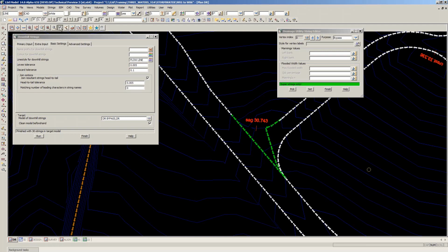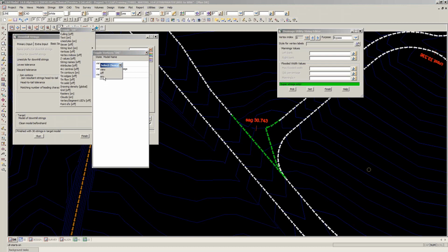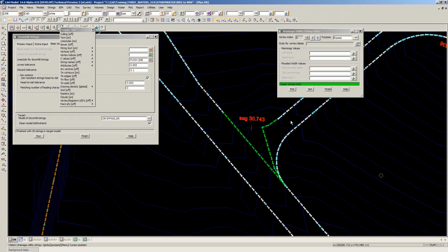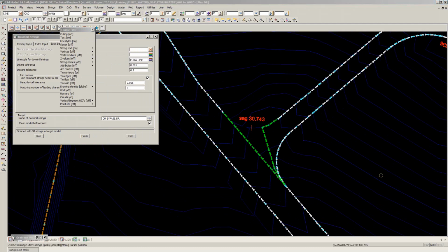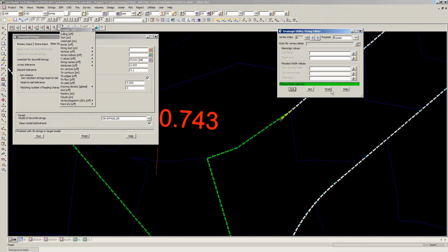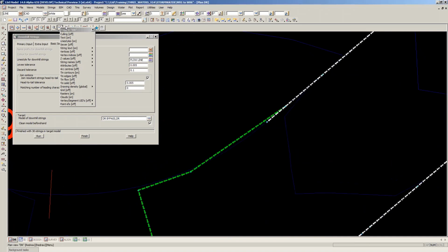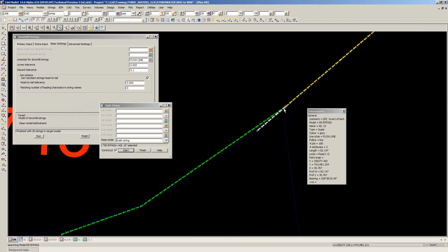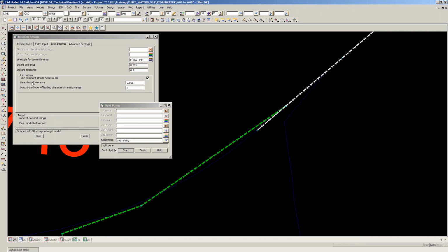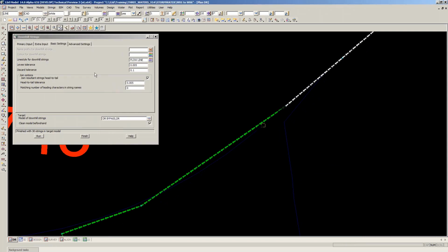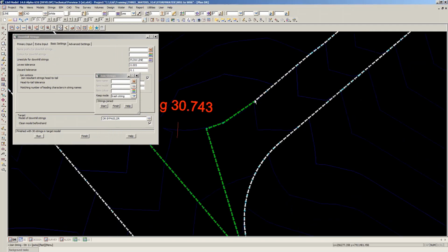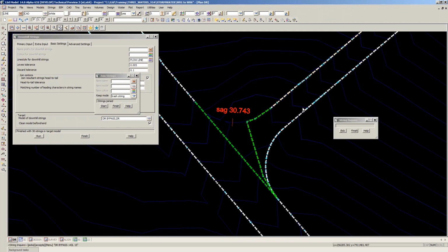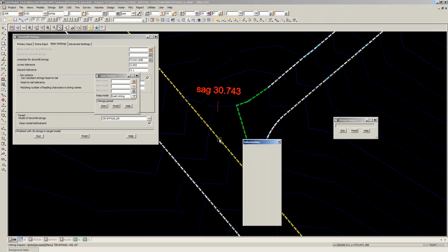First of all, I'm going to start off by highlighting the vertices here. So I'll just toggle on the vertices just for my bypass model. They're a little bit hard to see in cyan, but I'm going to use the pick button there and jump right on the beginning of, actually I missed a step. I just wanted to do one other split there. Strings, edit, split, and I want to split this white string at the beginning of that green string, like so, and delete that bit and join that to that. So I now have one continuous line going down to this point, this curly one going down to that point as well, and this one is nice and continuous. Okay.